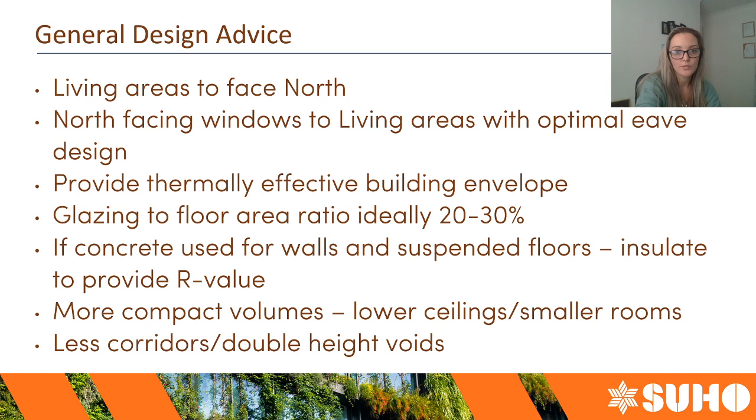If you use concrete for your walls and suspended floors, insulating those concrete areas is a good idea. Uninsulated thermal mass works well if it's designed in certain areas of the house with certain sun angles in mind.